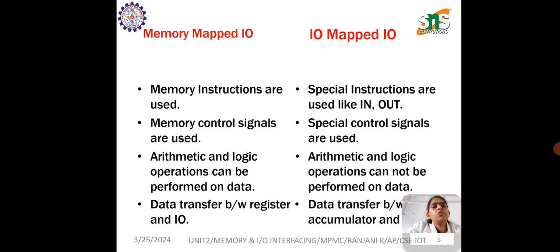There are two ways of communication by which the microprocessor connects with the outside world. One is the serial communication interface, and the other is the parallel communication interface. In the serial communication interface, the interface gets a single byte of data from the microprocessor and sends it bit by bit to the other system serially, and similarly vice versa. In the parallel communication interface, the interface gets a byte of data from the microprocessor and sends it to the other system in parallel fashion, which is similar to synchronous and asynchronous data transfer.